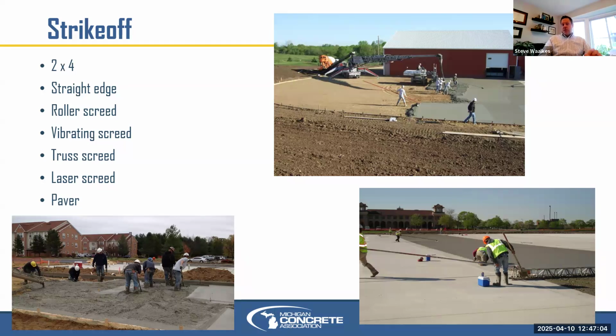You can also use crushed concrete as the 21AA material if you're in an urban area where you've got recycled concrete available. It locks in really nice and tight, yet still has some void structure to it. It doesn't hold water, generally, in most situations, and has some drainability to it.